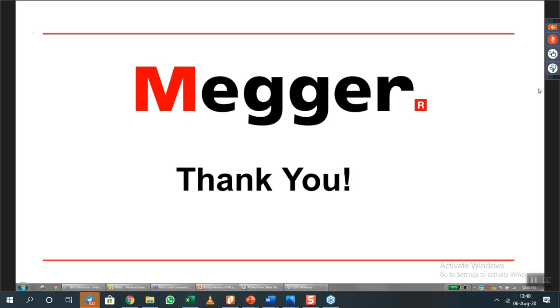No. Maybe he misunderstood. There will be capacitive charging also when AC is applied, but that will happen very, very fast. And so in my illustration during the presentation, that is only just an illustration. But of course, when an AC is applied, you will have a capacitive charging as well. But that happens in a rapid way, so that could be charged immediately. And we know why when you have this AC applied in for example, a motor, and you have a problem in a power quality, that capacitive charging could be discharged in a much higher voltage. So it happens with the AC insulation, with the AC voltage also.